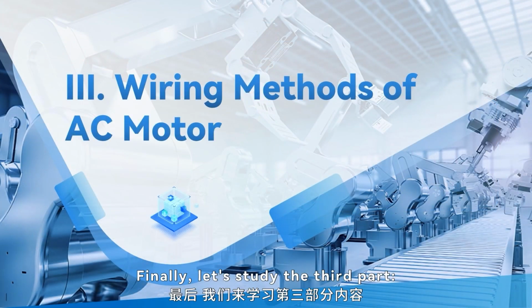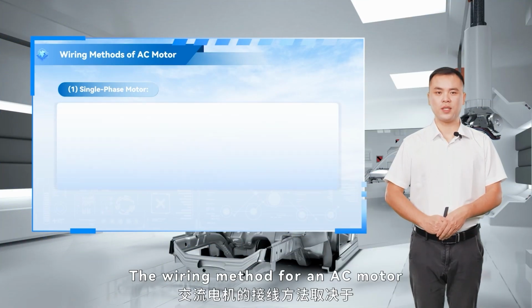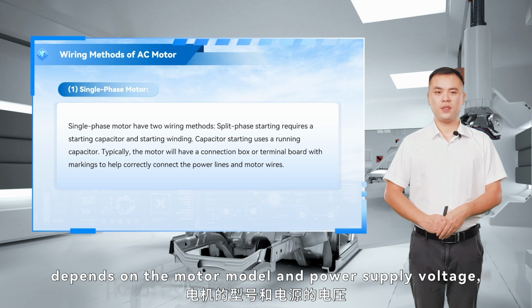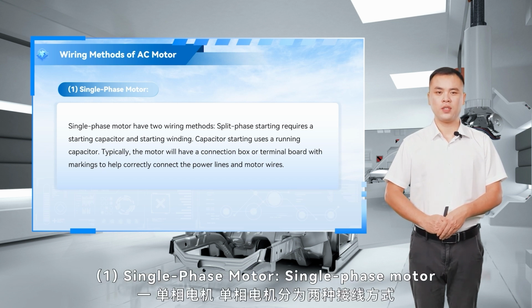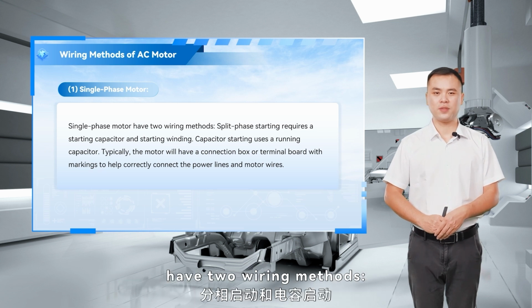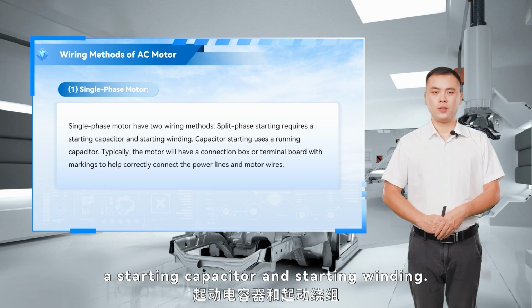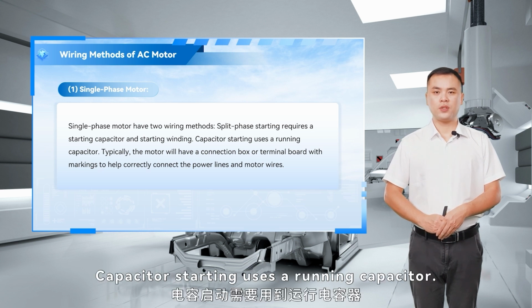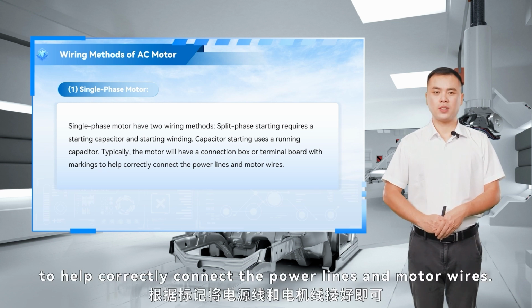Finally, let's study the third part: wiring methods for AC motor. The wiring method for an AC motor depends on the motor model and power supply voltage. There are common methods. 1. Single-phase motor. Single-phase motor have two wiring methods. Split-phase starting requires a starting capacitor and starting winding. Capacitor starting uses a running capacitor. Typically, the motor will have a connection box or terminal board with markings to help correctly connect the power lines and motor wires.